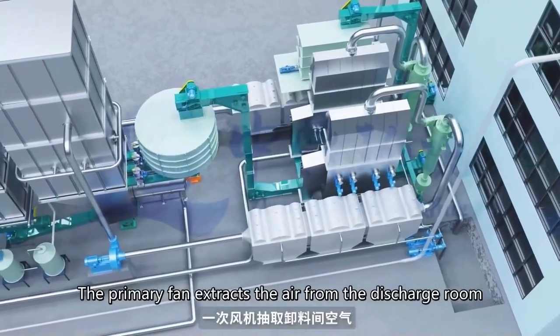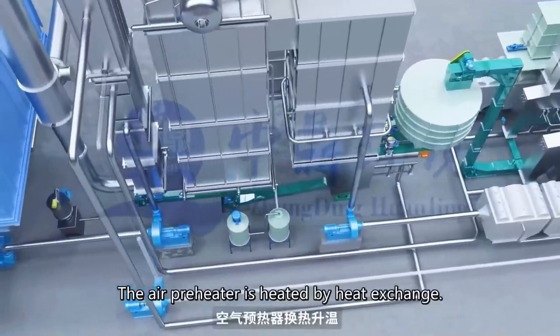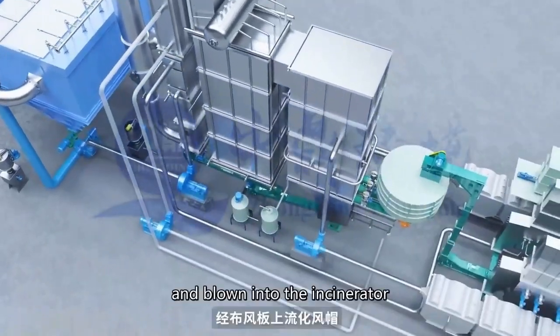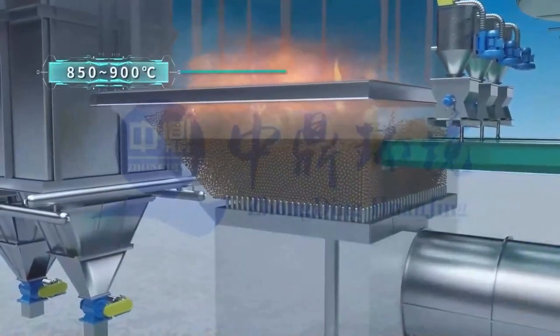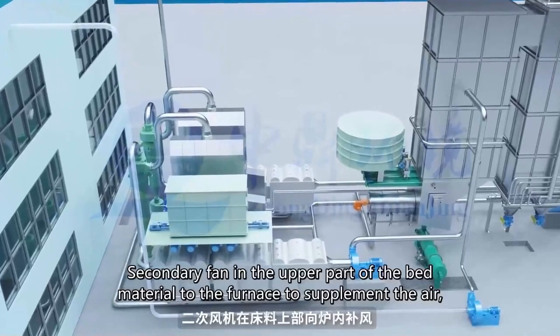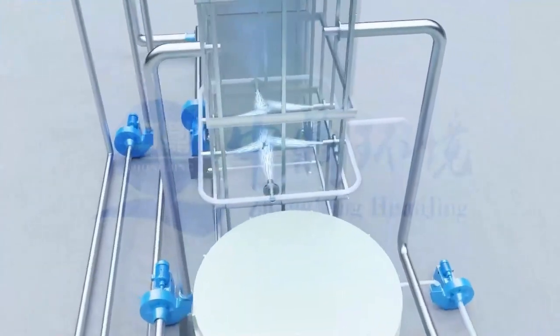The primary fan extracts air from the unloading space and sends it to the heat recovery system. The air preheater exchanges heat and warms the air, which is then sent to the bottom sealing chamber of the incinerator. The fluidized air blown into the incinerator through the air distribution plate causes the bed material to fluidize. The secondary fan supplies air to the top of the bed material, ensuring thorough incineration of sludge.